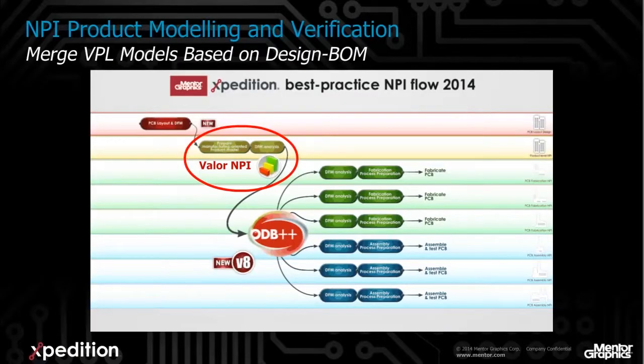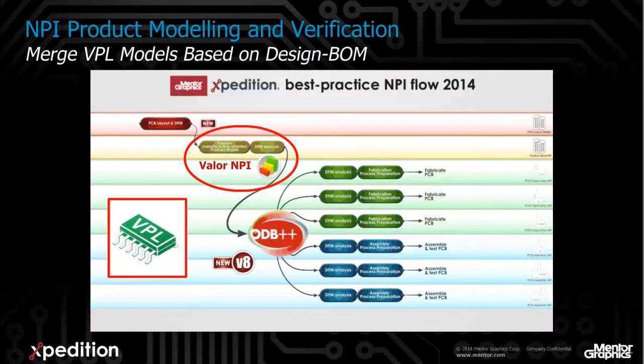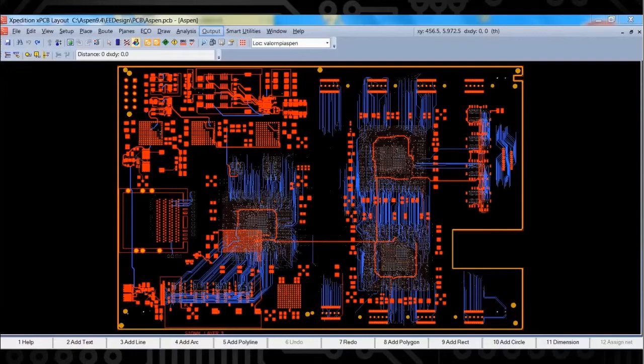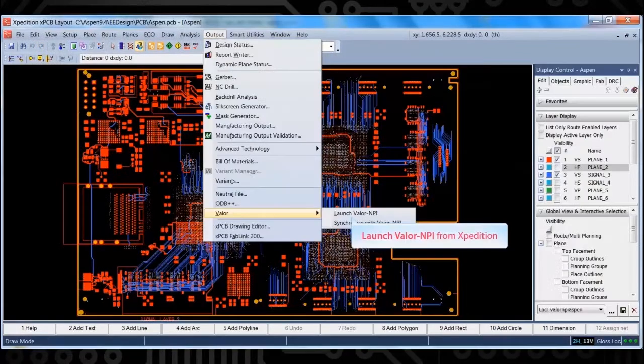Now we look at further left-shifted product NPI work that can be completed before handoff to the manufacturers. We start with a full validation of the assembly and test processes, taking into account all possible purchasable parts on the approved vendors list or master parts list.